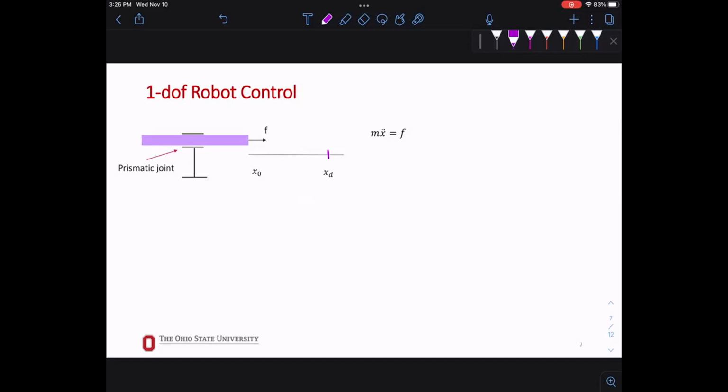We discussed mass spring systems, briefly on Monday. All right. So let's say this has a mass of M, and I'm going to pull this with a force, so there's an input force. It creates an acceleration. If you look at the dynamics of this system, we don't have any friction here. Do you remember m x double dot plus b x dot plus k x equal to 0, the mass spring damper system? We don't have a spring here. We don't have any damping.